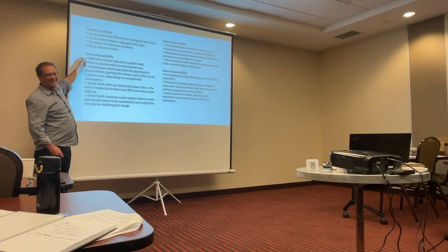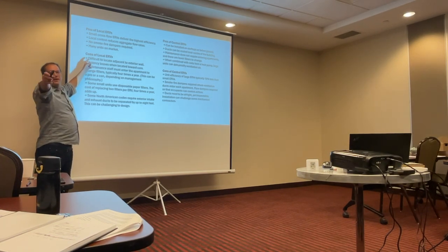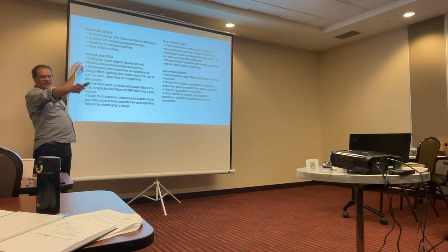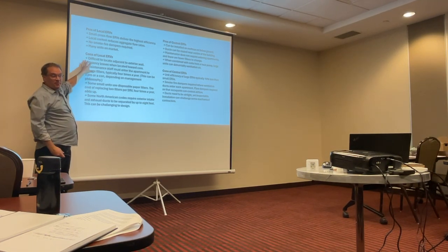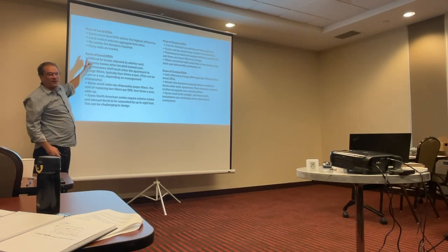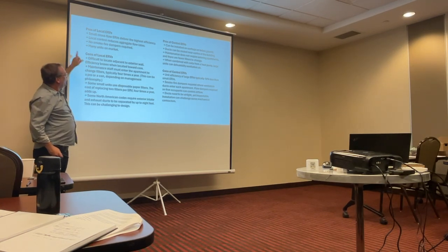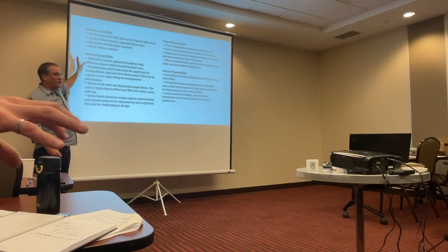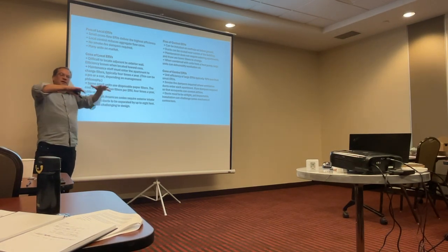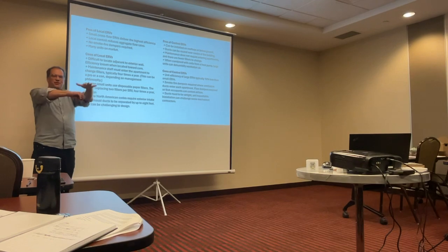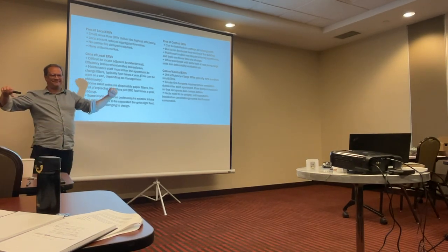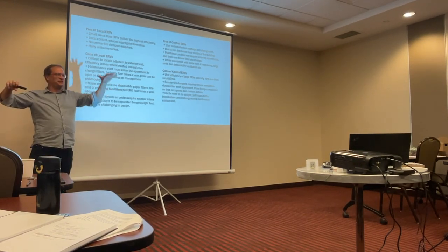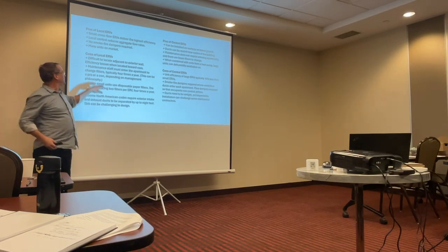Just ask, is this independent of whether the outside air is coming in centrally? We need diagrams for what he's saying, where the outside air is coming from. Every apartment is different, but it could still be centralized. We need diagrams. We have more local than centralized. The cons are, it can be difficult to locate. Those are on just one outside wall. And if you don't put it on an outside wall, you have some ducting, and that's a different strategy. You've got some duct losses, and then you don't have a high efficiency unit anymore.